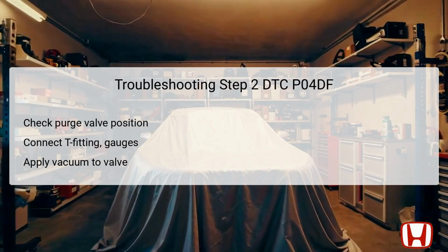EVAP canister purge valve. To begin, carefully remove the valve while keeping its connector and vacuum hose in place.